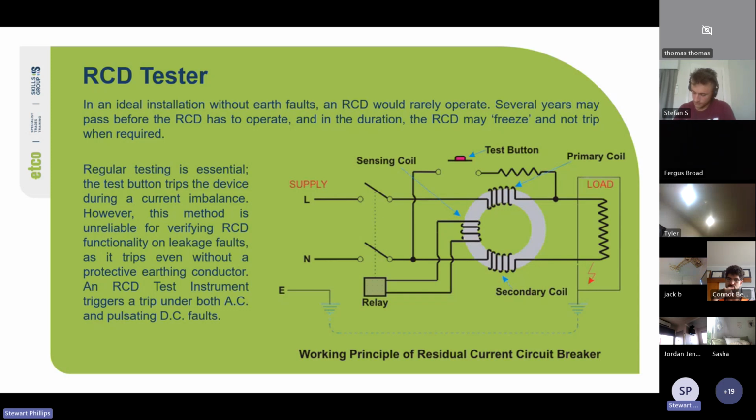Now, domestic installation, you need to push the RCD test button every 6 months. So every 6 months, you need to at least push the test button on the RCD. One good thing to test would be every 6 months do an RCD test, but obviously no one's going to do that. And not everyone who lives in a domestic property knows about this rule.